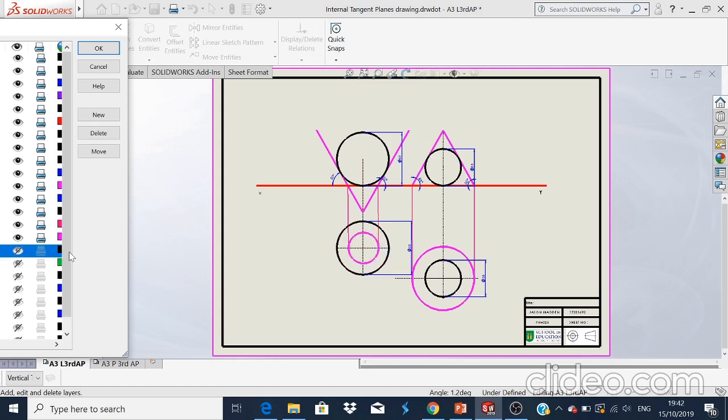So what we do is we draw a line parallel, tangent to both of these new pink circles, that's roughly in contact in one point. We project that up to the XY line. So the next point, this is called the green line here, is the oblique point projection method. We draw a line parallel to this horizontal trace here. We draw that parallel with our sliding set squares, and that's brought up to here, the XY line.